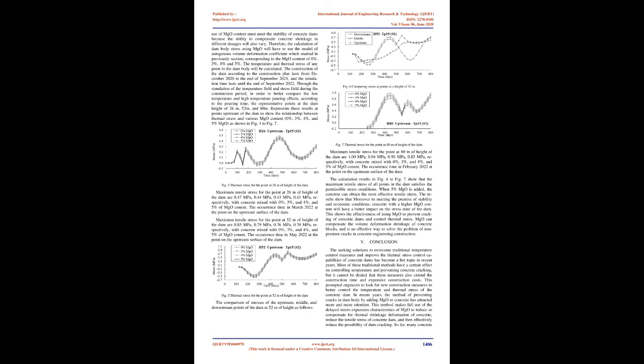In this section, a three-dimensional finite element numerical simulation model was established to consider the thermal stress compensation efficiency of concrete mixed with different amounts of MgO expansion agent. This section simulates the construction process of the Linxihe arch dam, and the sequence of concrete pouring over time through a three-dimensional finite element method, FEM. The calculation model is mainly shown in Fig 3.